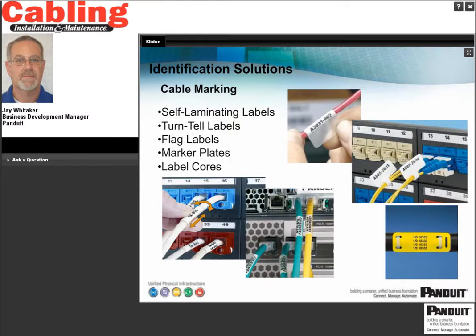Thank you, Jay. Another one asks about when cables penetrate walls or floor-to-ceiling penetrations. Is there a need or a requirement to label at those penetrations when they go through a wall or through a floor-ceiling combination? Yes, that's the firestop labeling and administration, and that's clearly defined in the standard as far as where you'd want to put those labels and what the information should have. Of course, you're going to label both sides of that penetration, whether it's each side of the wall or above and below a floor-ceiling penetration.